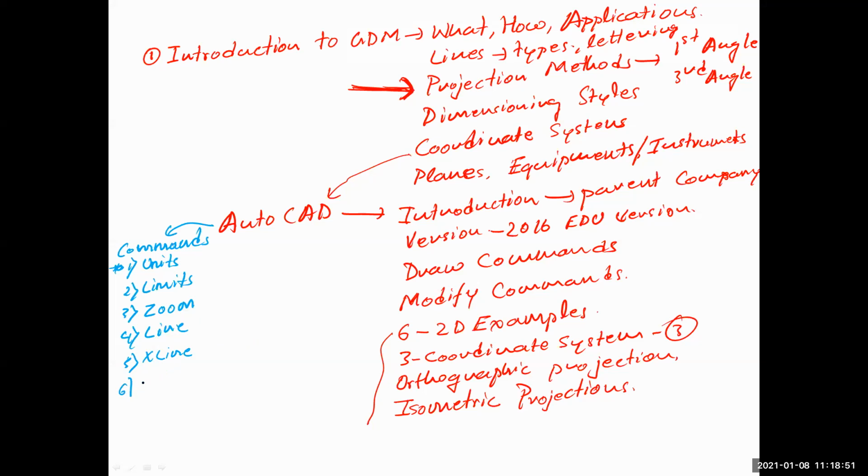You have seen how to draw circle. Rectangle. Again in circle, questions can be asked, what are the different ways you can draw a circle in your AutoCAD? So we can specify the center and give the diameter. You can specify the center and you can give the radius. There is one more method, tangent, tangent, radius. Okay, what is this option? I will show you.